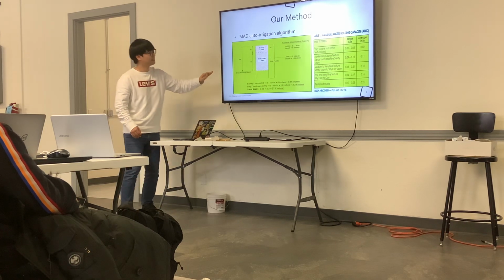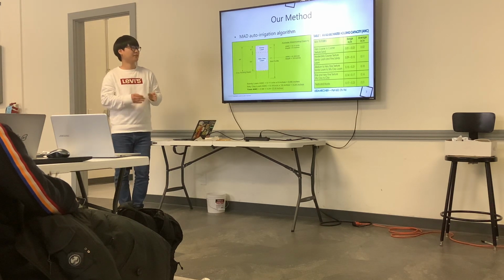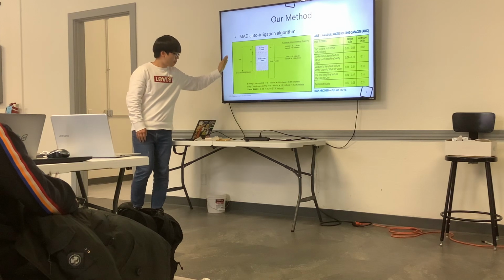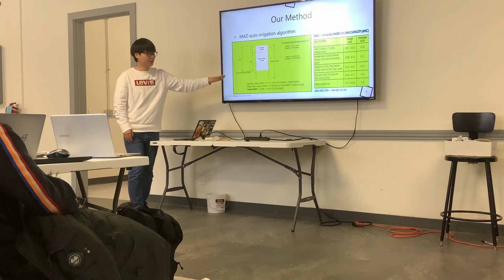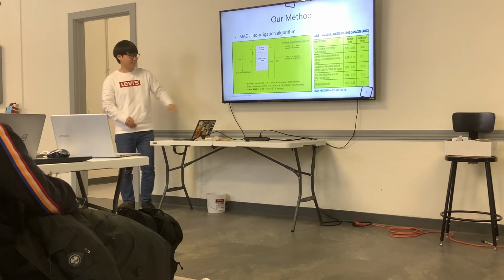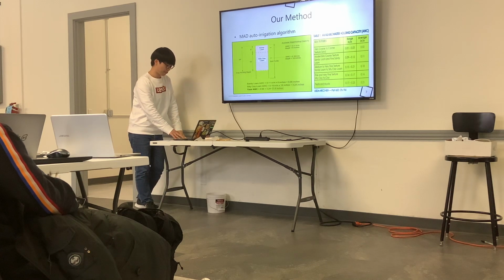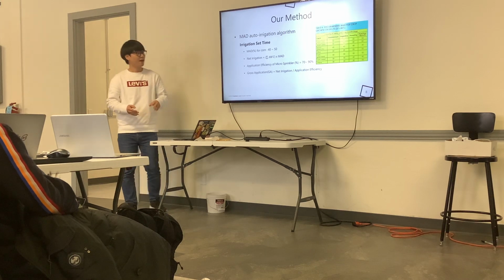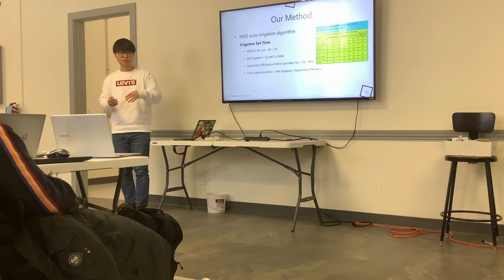So this part is silty clay loam. Silty clay loam average AWC is 0.18 and depth is 18 inches. So silty clay loam AWC is 3.24 inches. So total AWC is 3.9 inches. Using that, we can get how much you have to water.